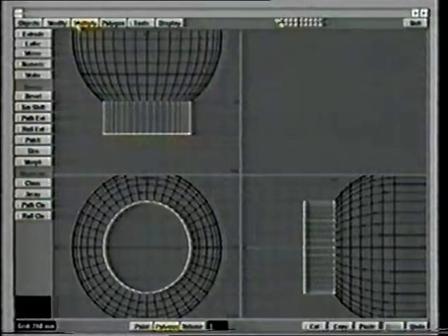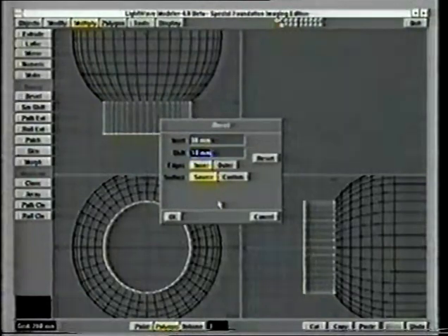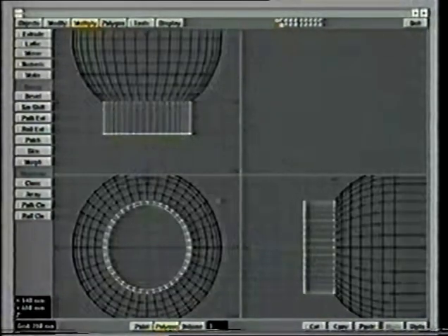And it's something that you have to keep in mind when you're making computer models, that even though sometimes it might look like it's going to be right, it will just have that artificial feel to it. It won't look like material has any thickness. So let's continue on here. I'm going to use bevel again. I'm going to use an inset of 30 millimeters and a shift of 0 this time. So what I'm doing there is creating thickness.